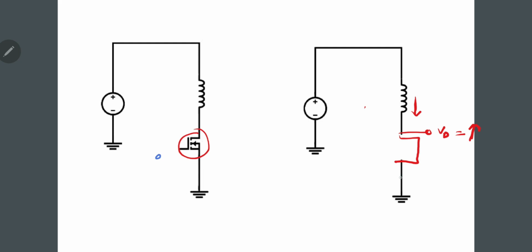So in order to avoid this situation, we must create a path here, and a path in such a way that the drain voltage doesn't get too high, or get to a level that can damage our MOSFET permanently. So in order to create a path for this stored energy to get dissipated, we can create a path using a capacitor and a resistor here.